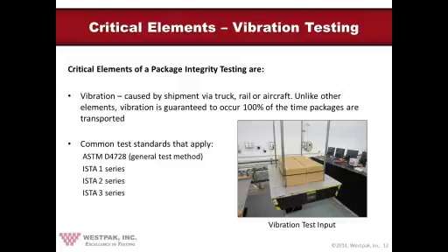The machines shown here can be programmed to simulate vibration resulting from various modes of transportation, truck, air, rail. And if you were doing a saver or environmental study, such as the ones using the savers we talked about, you can directly input what you measure into these tables, and they would reproduce that spectrum. The vibration is typically split between the three mutually perpendicular axes and usually consists of 2 to 3 hours total during a test.